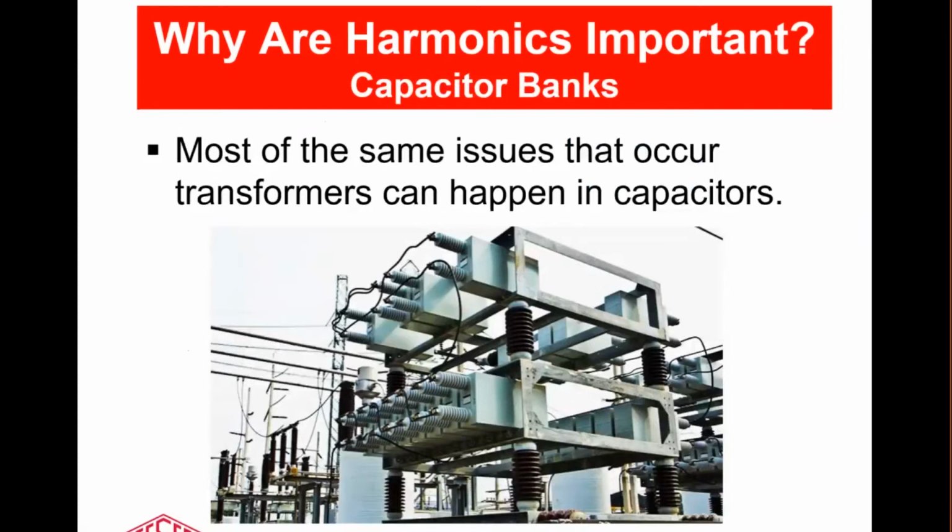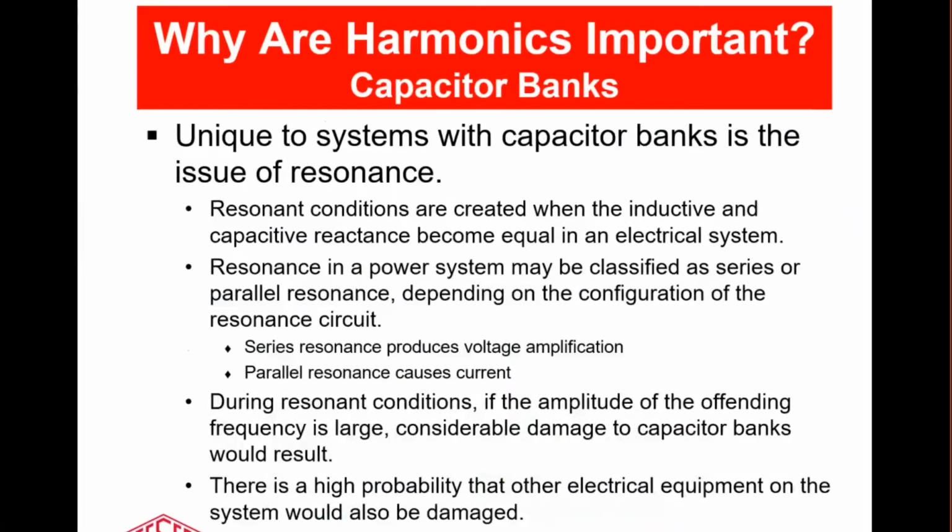There are a lot of the same issues in terms of insulation stress and other things in capacitors, but there's a unique problem in capacitors that can be extremely detrimental and destructive. And that is the issue of resonance phenomena. When a capacitor is paired with an inductor, it forms a resonant circuit.